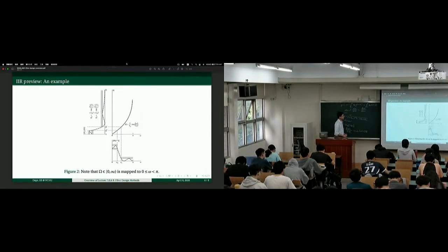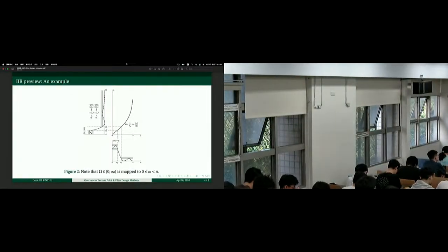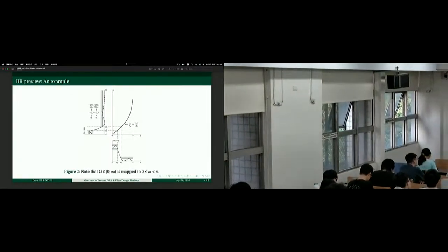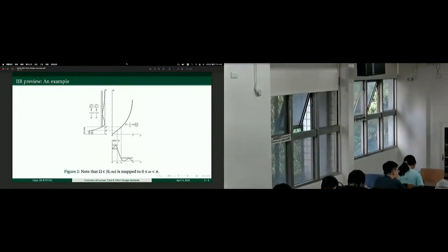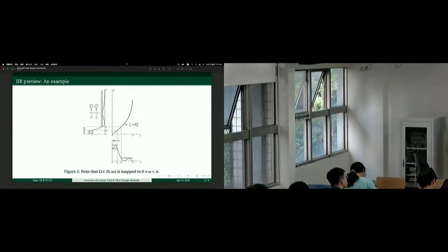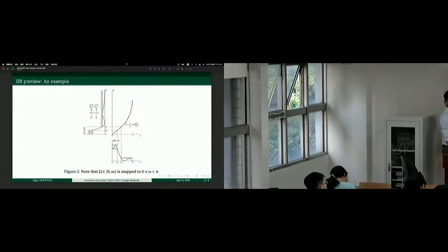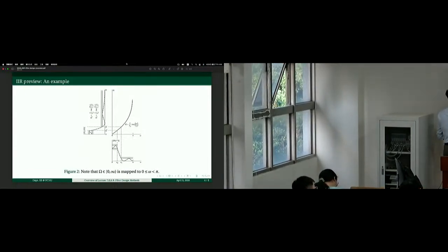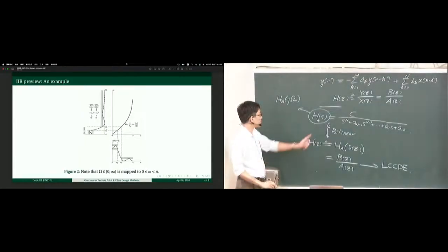And so here is another look. Suppose that we have an analog prototype and we want to evaluate its frequency response. That can be simply done by evaluating this system on the imaginary axis. Just substitute S equals j big omega.